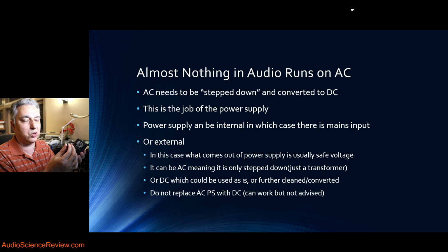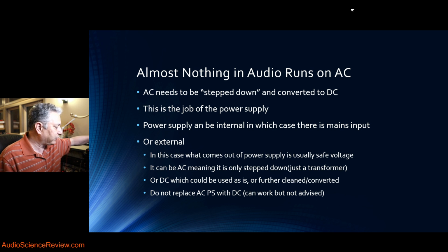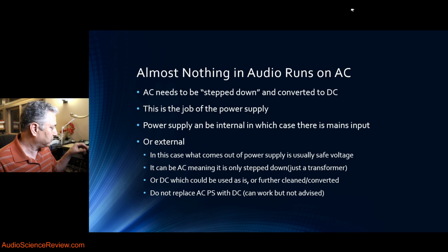If you actually measure with no load, maybe 6 or 7 volts. And generally, you don't want to feed devices designed for DC with AC input, or feed it DC and vice versa. So don't mix the types. I don't want to get into a complicated discussion of when it can work. It is possible for it to work, but at a high level, don't confuse one for the other.